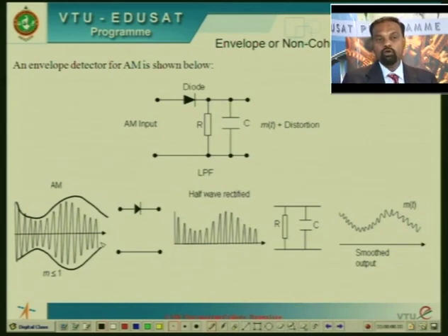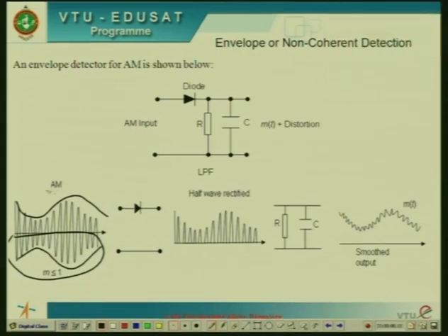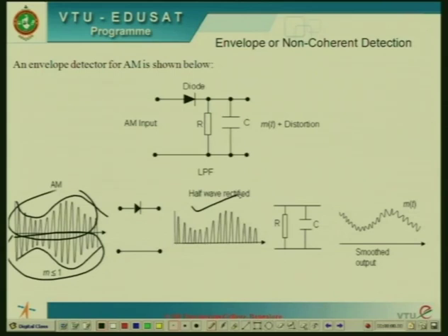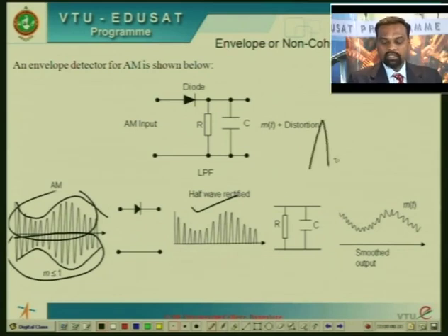So what will the diode now do? Because the diode is working as a rectifier, whenever the signal is applied, it will cut off all the signals on the bottom side, because they are all less than the cut-in voltage of the diode. All the positive data available here is available at the output of the diode. Now if you look at the positive voltage, they are all like pulses, like this.